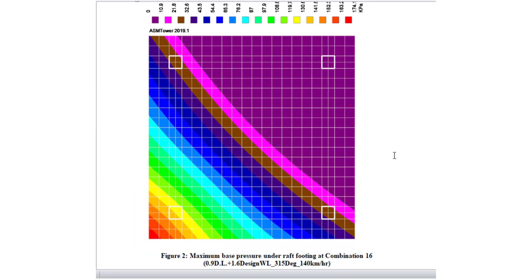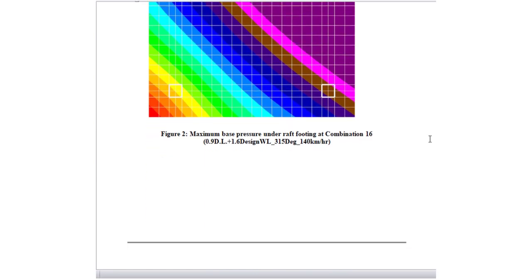Suppose there are imaginary lines between different stress categories. These lines are not straight lines, but rather curved lines. In approximate stress calculation methods that assume the rigidity of the foundations, these lines are straight. The smaller the thickness of the foundations, the more curvature of these lines due to the flexibility of the foundations.